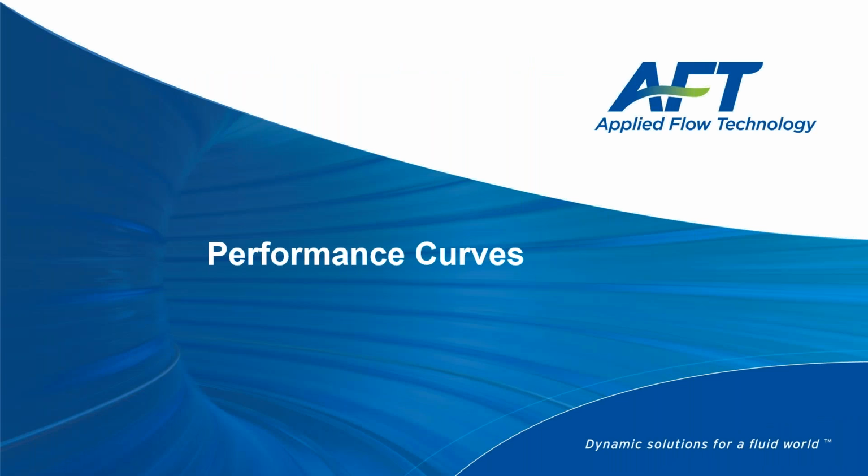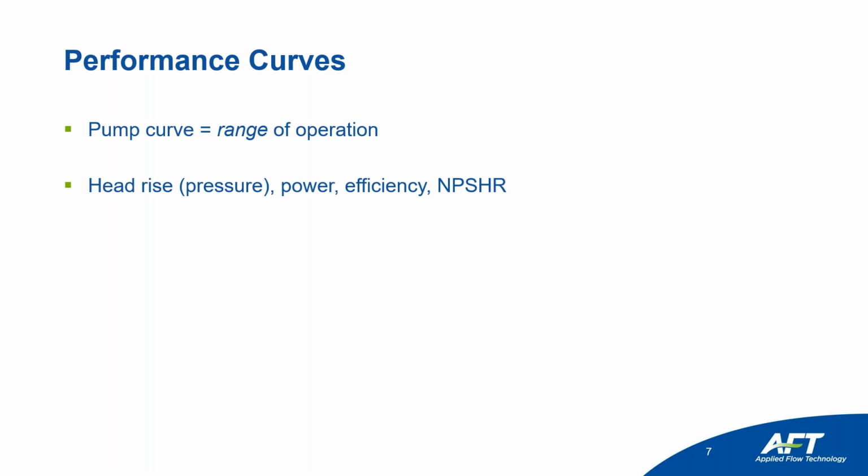Okay, now let's get into the first topic, performance curves, or what I call the perf curve. Performance curves, okay. That's a pump curve, right? There's a range of operation. The fact that you're on a curve means there's a range. These curves will have a few different things. They'll have head rise, or pressure you can think of, power, efficiency, and NPSHR, net positive suction head required.